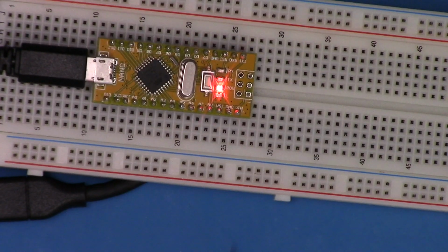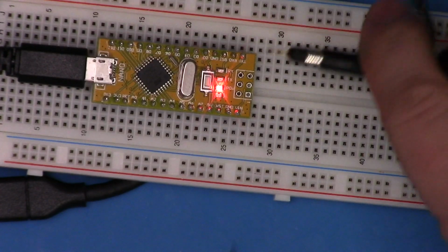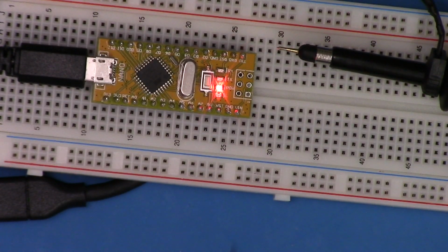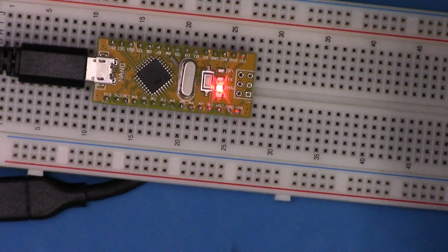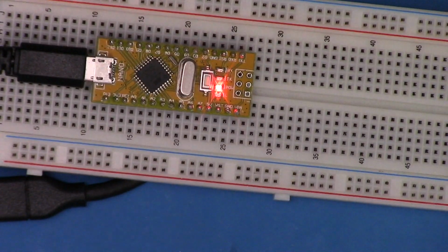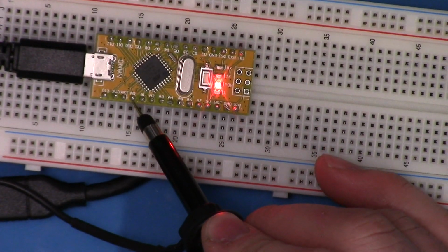But what we expect is that the lowest most bit, for example, is going to be toggling because it's counting up. So as we look at different output bits, I'm going to use a little oscilloscope here, we should see different data toggling. So for example, we could start with A0. So just take your scope probe and you could put it right onto A0.